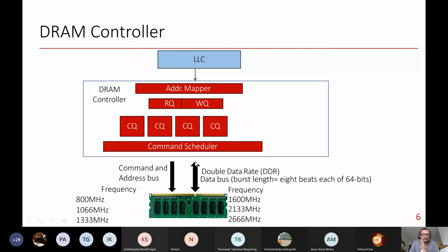The semantic meaning of changing the direction is that the control will say that now data will move from the DRAM controller to DRAM. And if you are loading something, then the controller will say, okay, you are getting the data from DRAM towards the DRAM controller. It has its own latency also. So depending on how frequently you write, it can also affect your read, and eventually it can affect your latency, execution time and all.